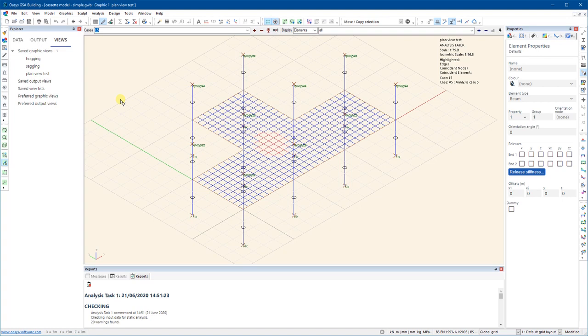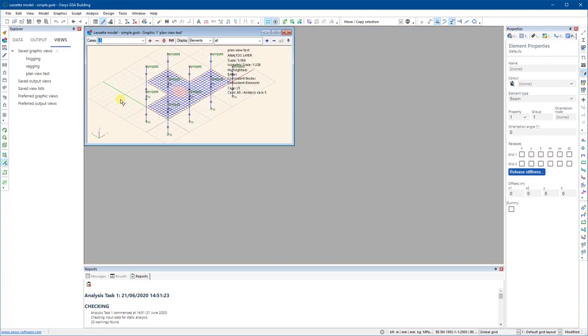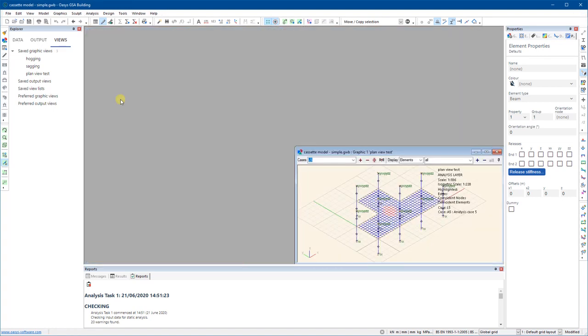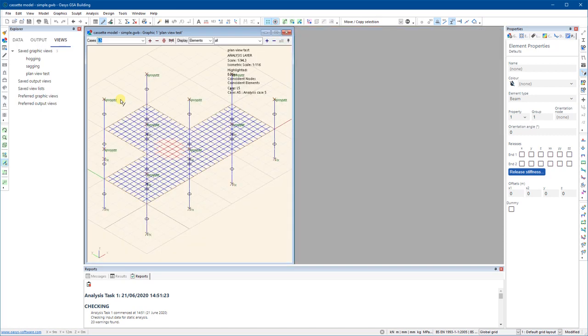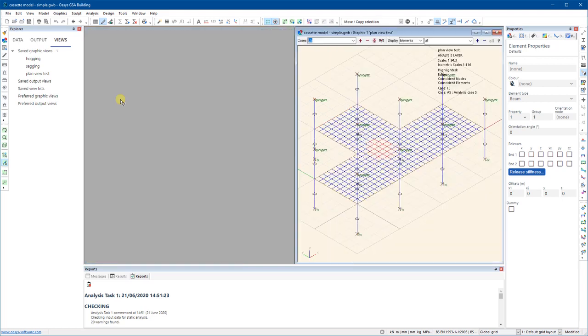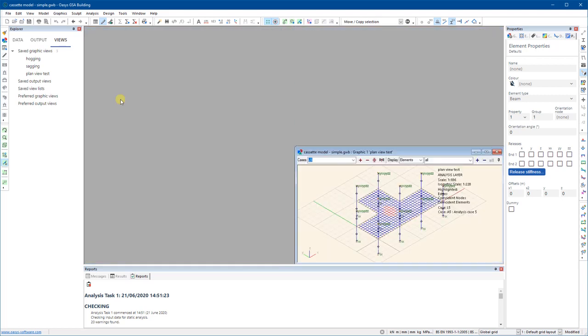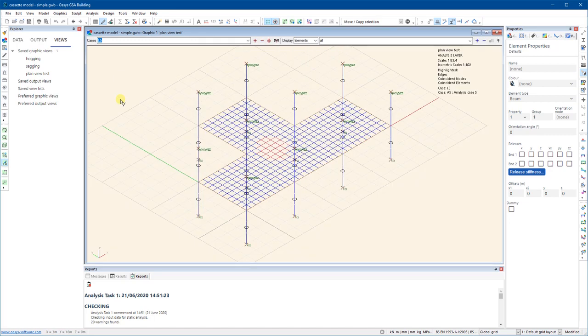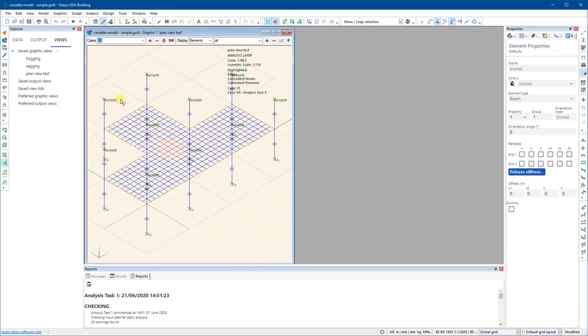So going back to the idea of hotkeys, one of the other useful hotkey combinations is that if you press Control and then press the keys on the number pad on the keyboard, that moves the view to different positions. So I'm just holding down Control and pressing 4, so that does that. Press 6, that moves it across, and so on. Pressing 5 takes it back to that. But let me just do Control and 4 for that. So that's essentially the base model I have.